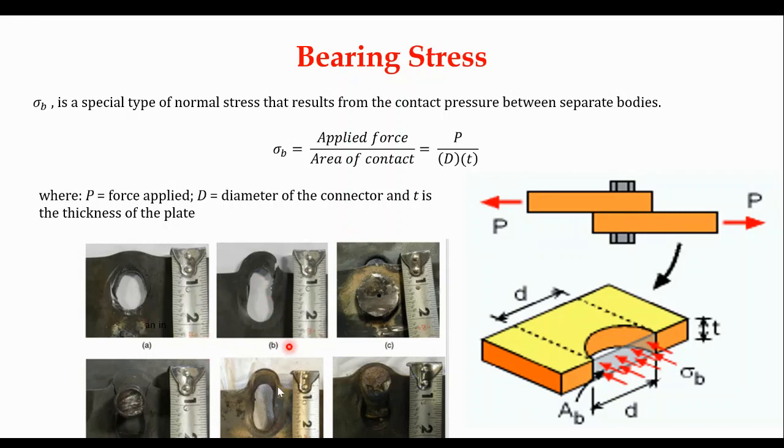So do we think that when the hole is like that, the connection is still okay? No, because the connector should be tightly fitted. It can no longer be allowed to move around in the hole. Otherwise, your connection is no longer strong. Just like in the BE building.